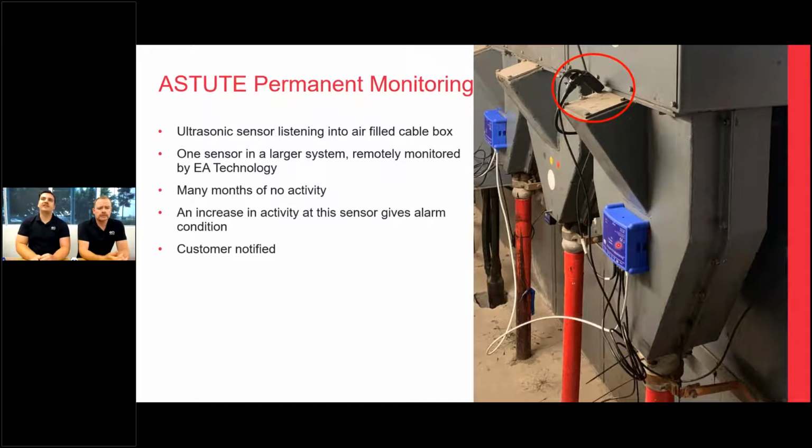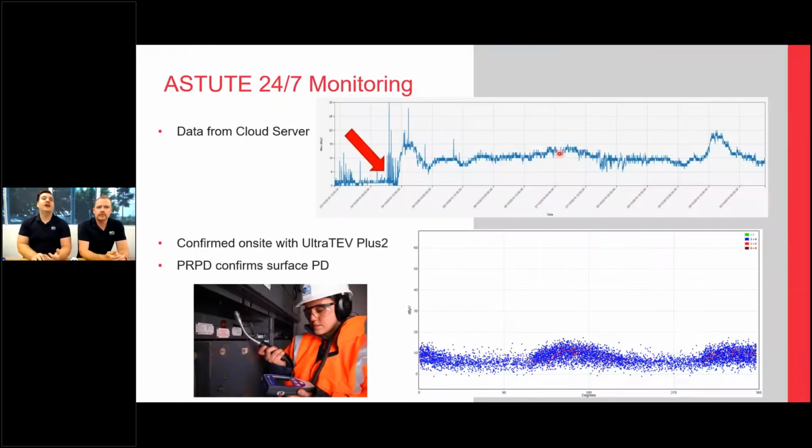In this particular case, we've got an ultrasonic probe here listening into this cable box. This is only a small part of the larger system, and I think we were monitoring it for about 3 months and there was absolutely no activity being picked up by this sensor at all. Then one day, we saw a sudden increase in activity on that ultrasonic sensor.